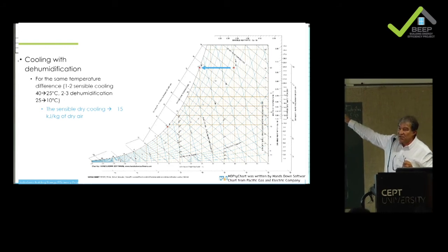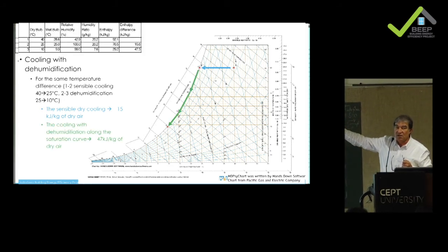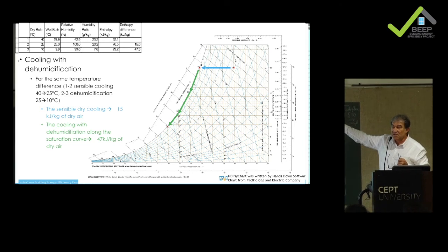Let's say you are coming directly with fresh air into a cooling coil, it's 40 outside, it's very humid. It's almost a lethal climate, what I have put here, but it was just to show. And here what you see is that in the cooling coil, it will start by cooling without dehumidifying. Actually, the real process would be more like that. But to make it easier to understand, it's like if you had, let's say, two cooling coils, one after the other.